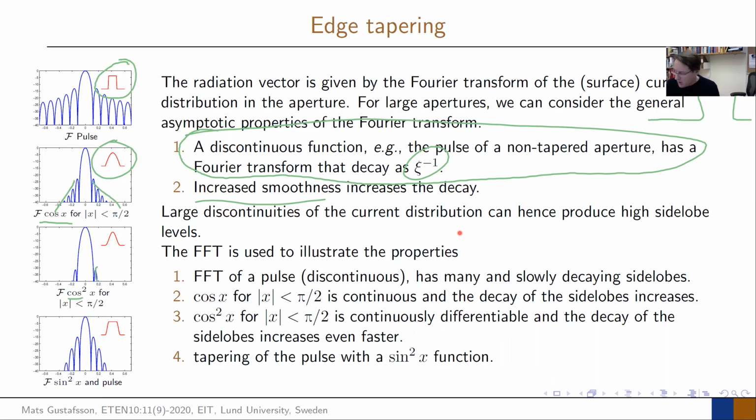And that's good. But of course, when you do that, you also use less power on the edges here, so you don't utilize your full aperture. And then you can say, let's compensate between those, so have almost maximum aperture in the center, and then a little bit smoother down, and then you are somewhere between these two levels. So this is the way you can play with your aperture illumination, because you want to use it as efficiently as possible.